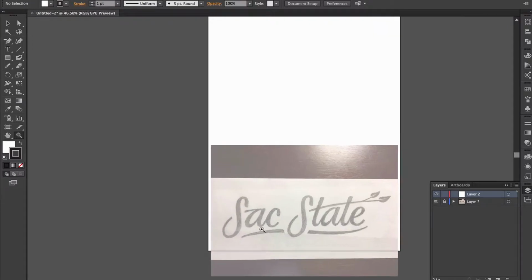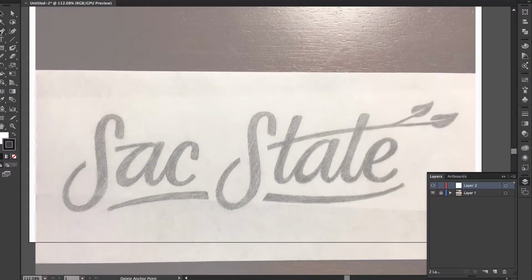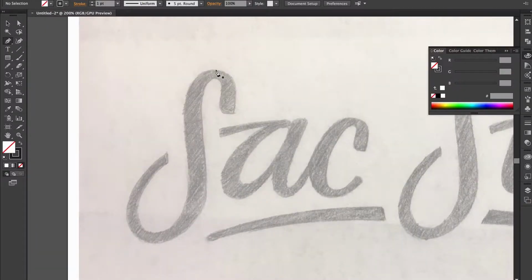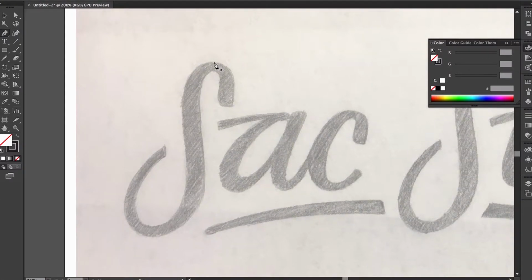You could just click and drag, and then go ahead and select the pen tool from the toolbar on the left. Now the pen tool works by creating lines and paths out of anchor points and Bezier curves. And these are good because you can create shapes out of these points and curves and have really smooth edges. And the way to plot these anchor points is by clicking on the extremities of curves as well as the places where there's a distinct change in direction.